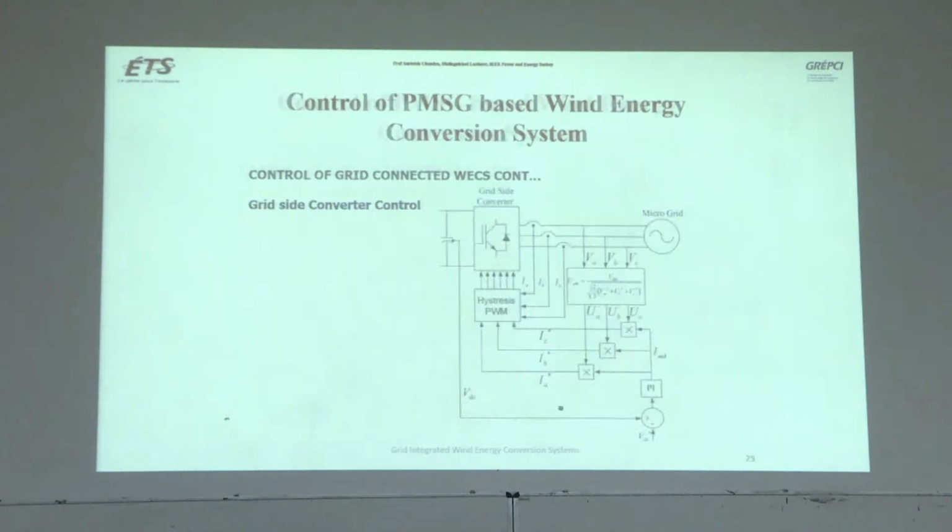So very simple control, and you can put it like this. Same thing as in the active shunt filter, we are putting the same thing. You are measuring VA, VB, VC, calculating the unit vector for the voltage UA, UB, UC. Okay, you are measuring the 3 grid currents IA, IB, IC, and here you see you have measured VDC.